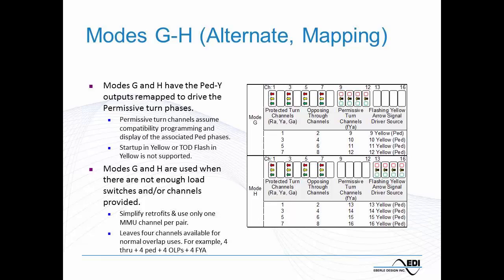It's very important, if you're setting up a new cabinet, we need to consider the monitor programming first to get these channel assignments, and then we can program the controller, because now we already know the phase to channel assignments that the MMU is requiring. The MMU in this case is kind of more restrictive than the programming we have in most modern controllers.